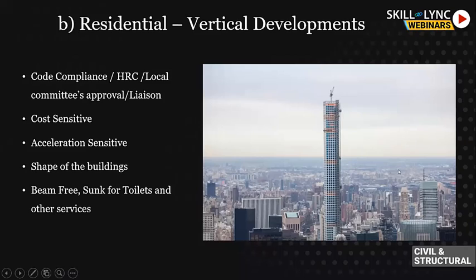The building in this photograph is one of the tall buildings of New York, but the challenges are very similar in New York and Mumbai. For example, we are at the seashore, and there's a huge amount of wind load that these buildings get exposed to. And when the building gets exposed to wind load, it tries to sway back and forth. So you also have to maintain the acceleration, since humans are staying in the building, so that it does not give higher acceleration, because people will start to feel nauseated. It's a very common thing to happen.